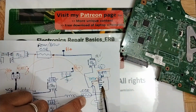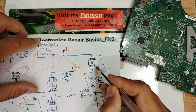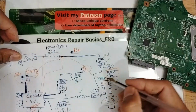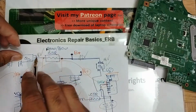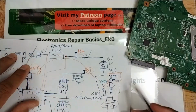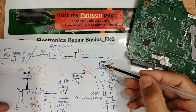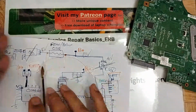But when the laptop works using the battery, here you will find 12 volt, and here 12 volt, but the 12 volt will not pass to this side. This one protects this side, and this one protects that side. When using the charger, this one protects the battery. When using the battery, this one protects the other components.